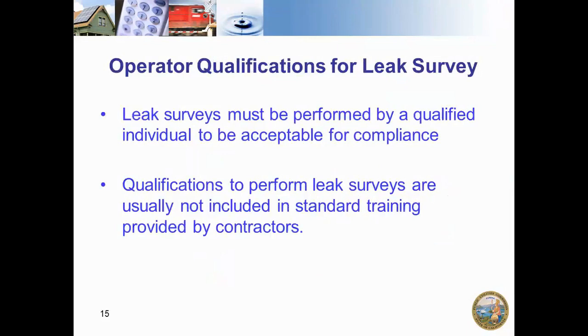For operator qualifications, the standard courses provided by third-party contractors frequently will not include leak survey as a part of their operator qualifications. So if you want to perform this yourself instead of contracting this out, you will have to be qualified in a manner that is outlined in your O&M. And if no such way to do that is in your O&M, then you will have to edit your O&M to allow that before you perform any leak surveys of your own.